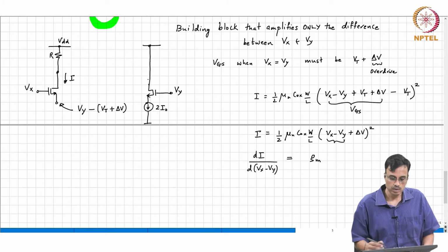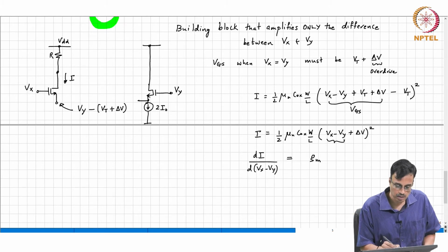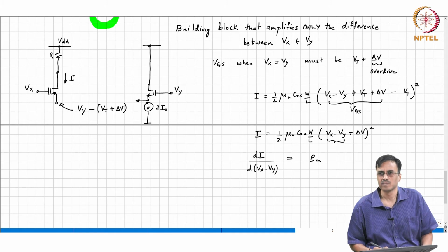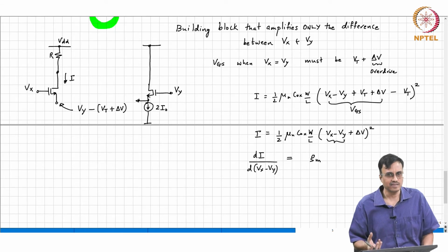What should we do? What is that voltage? Assume RO is infinity. Yeah. So, basically the voltage drop across the gate source is dependent on the size of the transistor and the current that you are pulling through it, correct.